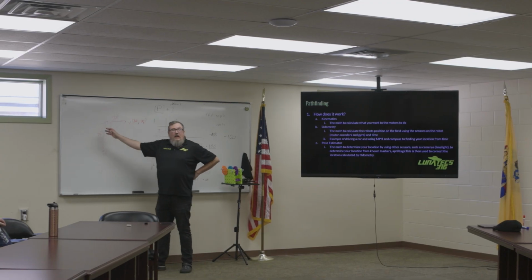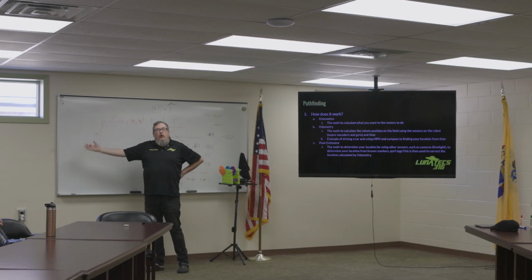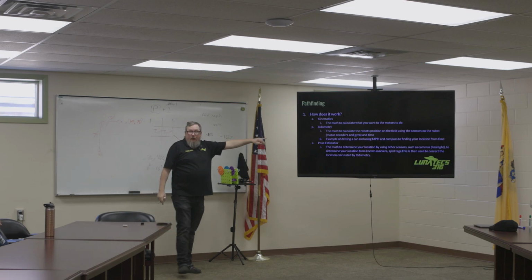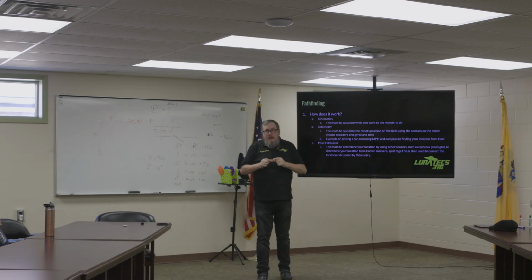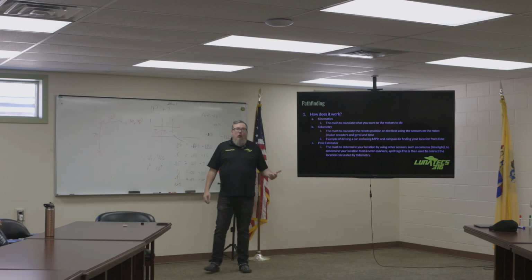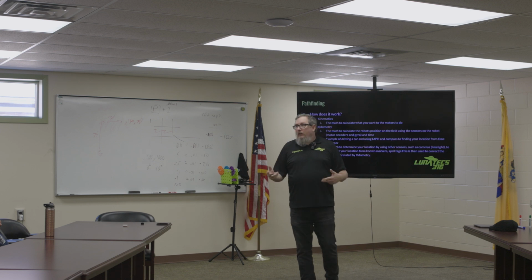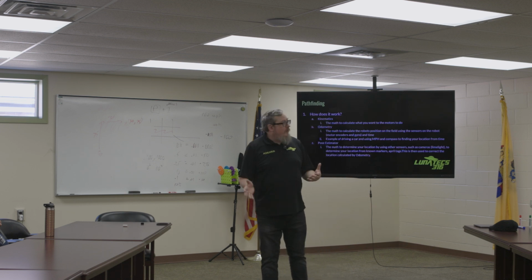So knowing how fast I'm going and how long I've traveled, I can calculate my position. That's what odometry is doing. So the odometry is measuring the robot, reading in the motors, knowing how fast the wheels are spinning over time, and calculating our position on the field.